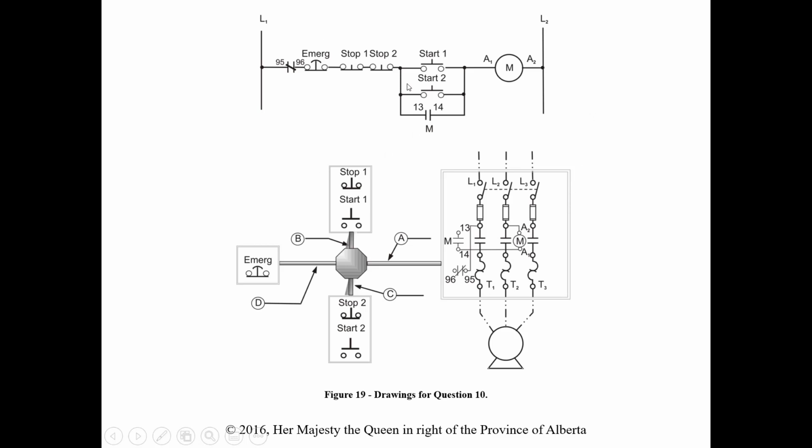Make sure and go ahead and give this a try. I won't go through and label this one right now because that's what the next module is all about, going from wiring diagrams to schematics. So give this a try. It gives you the answer in the module, but in my next video I'll definitely show us how to do this. What I do basically is I label each wire with a letter, and then I transfer the lettering down here, and then I draw it out, and it will tell you how many wires you need in each one of these. Just remember there's a junction here, so you can make splices here.